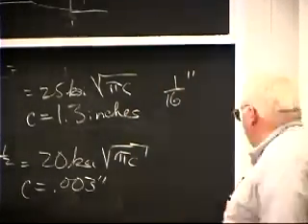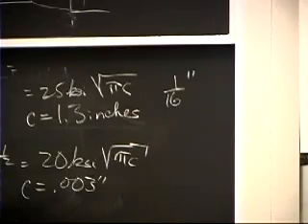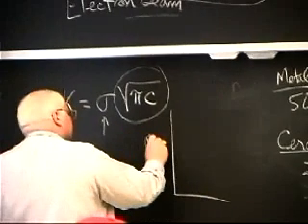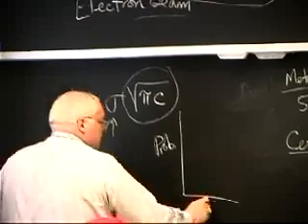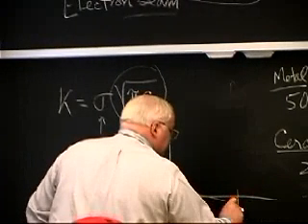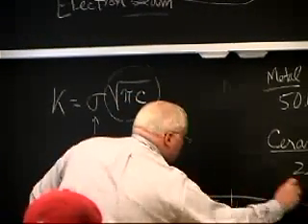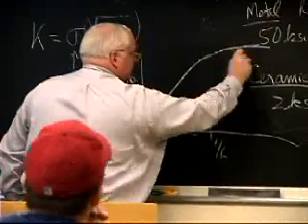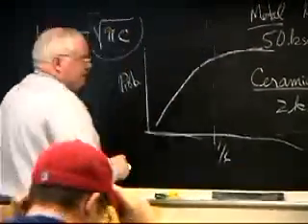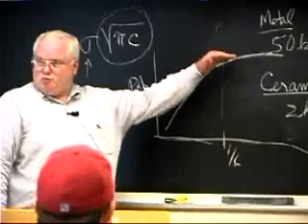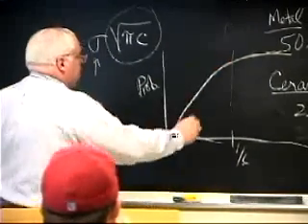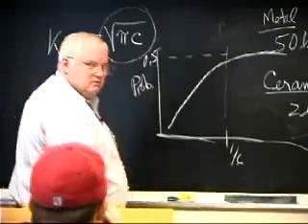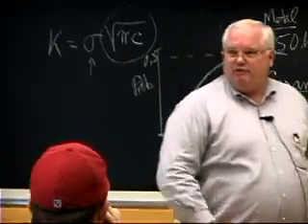And what reliability? In fact, I didn't make an overhead of it, but the curve for probability of detection versus flaw size, if this is 1/16 of an inch, the curve kind of goes up like this, okay? And there's your 1/16 of an inch. Now, the interesting thing is the probability of finding it there is about 1/2. And I don't care if it's a 3/8 inch flaw.